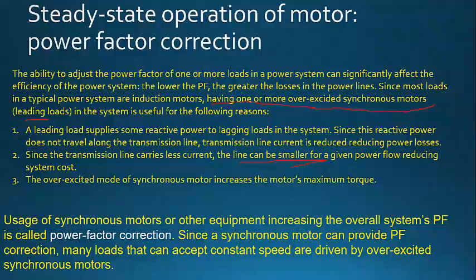Since a synchronous motor can provide power factor correction, many loads that can accept constant speed are driven by over-excited synchronous motors. All right. There are other methods that we can use to improve power factor, but for the sake of this course, we are only focusing on synchronous motors. When we get to power system operation and control, we will look at the other methods that we can use to improve power factor.